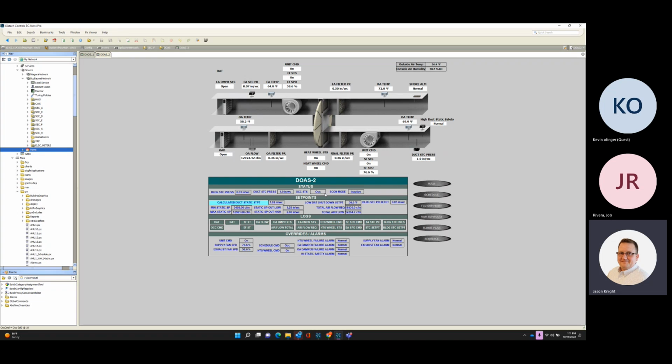So the key points, economizer mode. If the economizer mode is inactive, the wheel's on. The economizer mode's active, the wheel's off. It's just reverse. You can override your fan speeds. You shouldn't have to because everything's balanced and set, but obviously, doing maintenance, this or that, you want to do that at times. So those are overrideable.